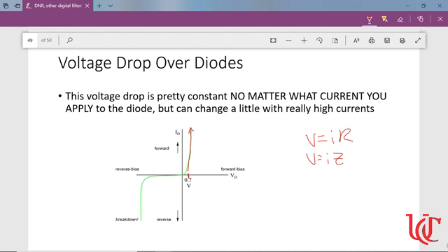In reverse, so I apply negative voltages, right? My x-axis here is voltage. If I'm applying negative voltage up to something, still very little current, or practically nothing, until I get to something high enough that it will even overcome that bigger depletion zone and is enough of a driving force. And then I do get current, negative current, because it's in the reverse direction. And this is what's called a breakdown. It's a reverse bias breakdown. So again, I'm trying not to allow any current through there, but up to some point you will if you apply a large enough driving force.